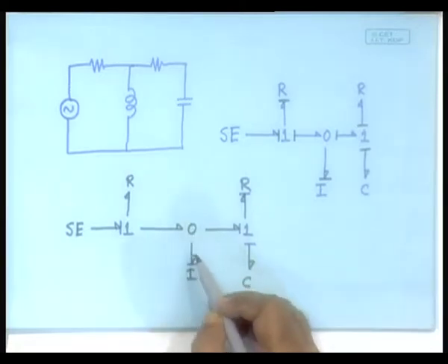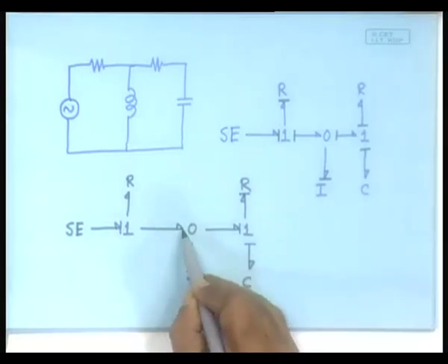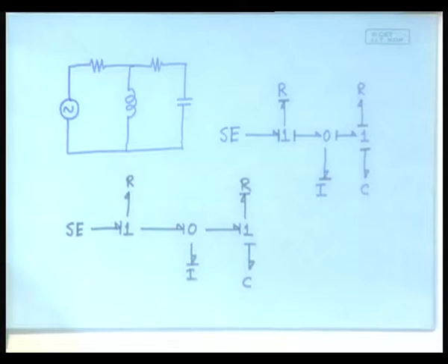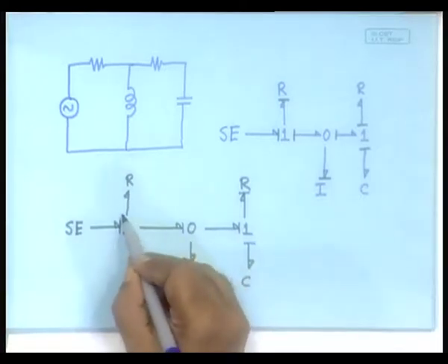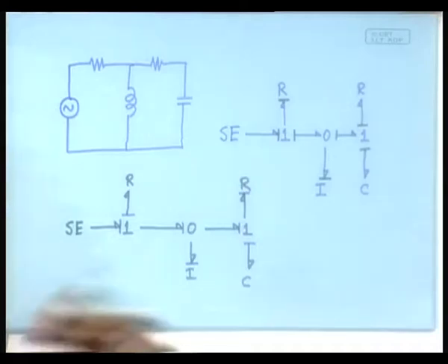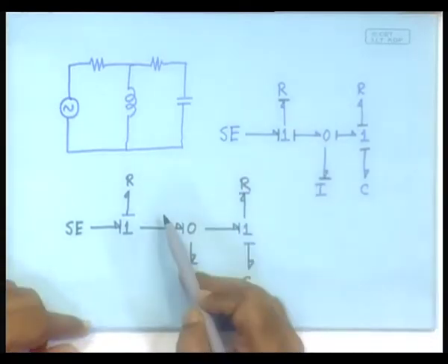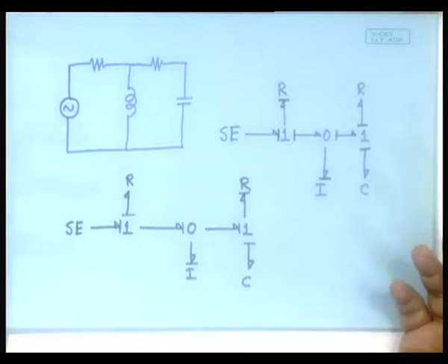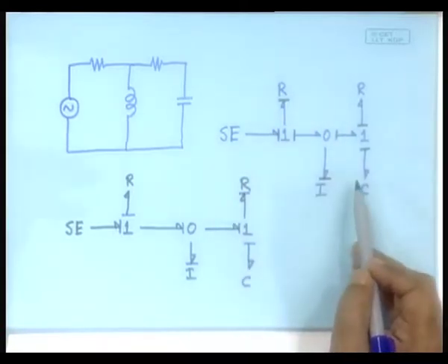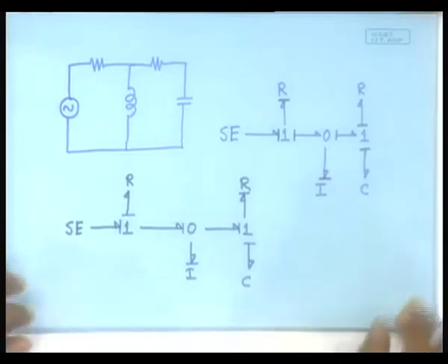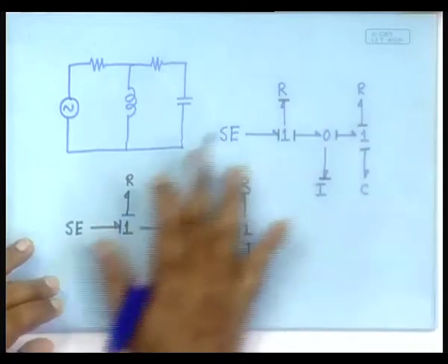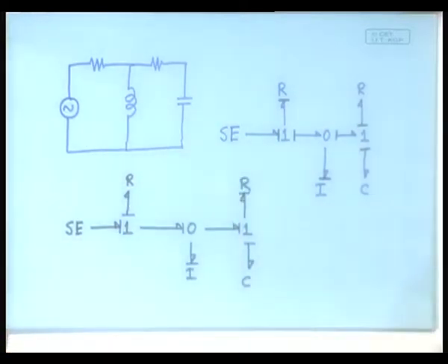So, this 0 junction has taken out the effort information, therefore, this bond must bring in the effort information like this. So, the flow information has gone to the one junction, it must distribute, again completed. But you see, this and that both are true, but they are differently causal. What does it physically mean? What it physically means, if you try to understand that, let us obtain the differential equation starting from this premise.